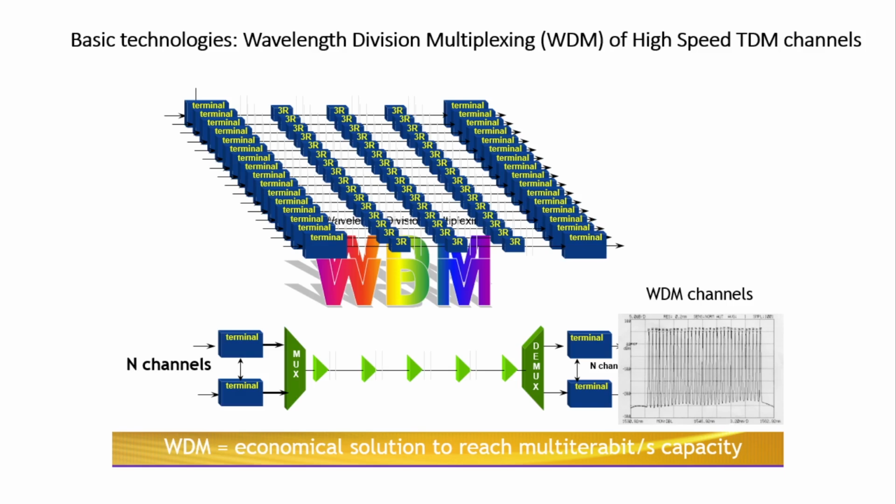After that, the signal is transmitted over the optical fiber cable, and on the receiver side there is a demux, which converts that single signal coming on the optical channel into n number of outputs having n channel terminals. This output is called WDM channels.